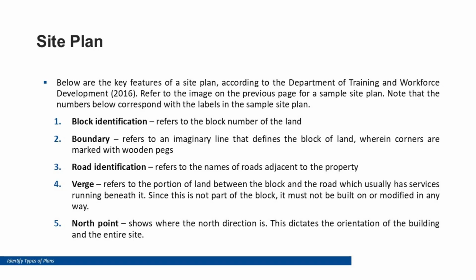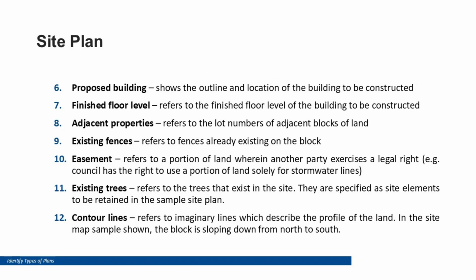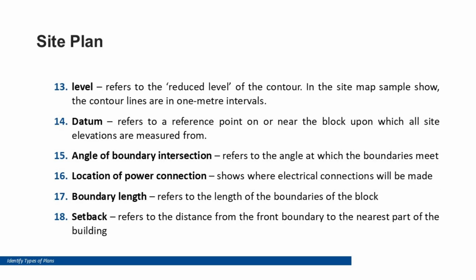Knowing how to read a site plan is crucial because it influences compliance, such as setback distances, drainage gradients, access routes, and construction staging. The title block will show the address. The drawing will show surrounding properties, access roads, and the exact orientation. A clear understanding of the site plan ensures that your construction activities occur in the right location and comply with planning requirements.